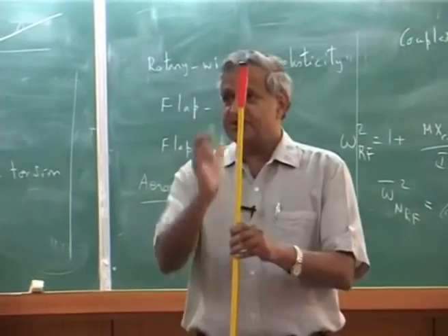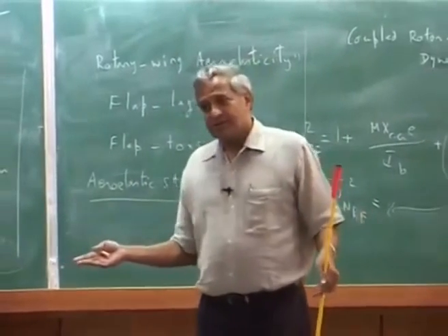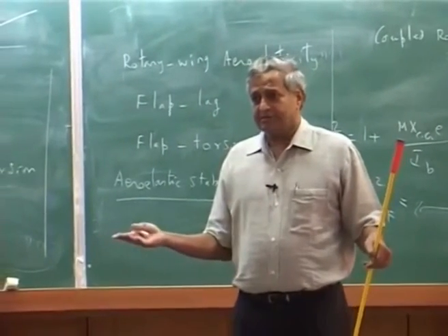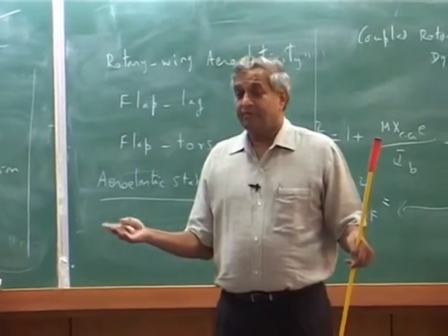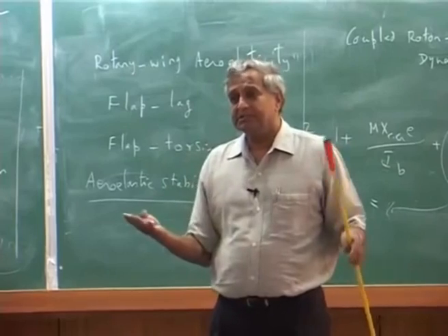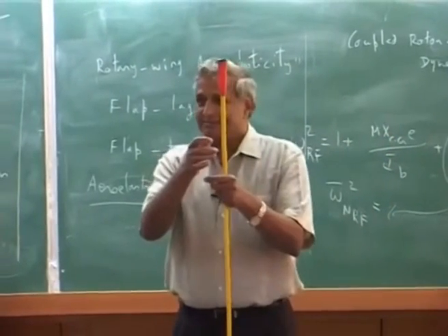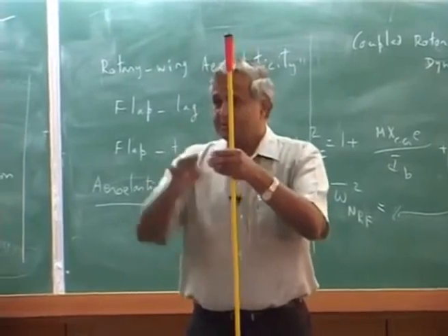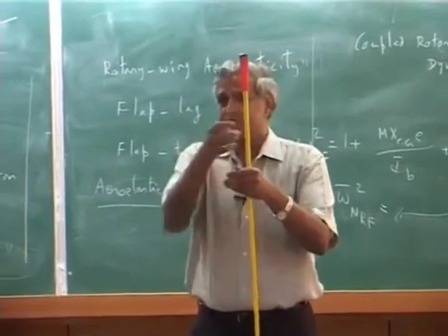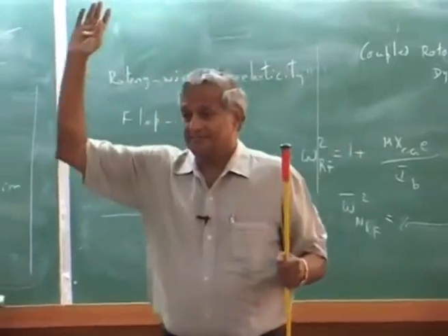If you take flap shear load, if it is a 4,000 kg helicopter, it is 40,000 Newton for 4 blades. That means per blade it is 10,000, to support the weight of the helicopter by 4 blades. Shear load 10,000, but centrifugal load is around 100,000.